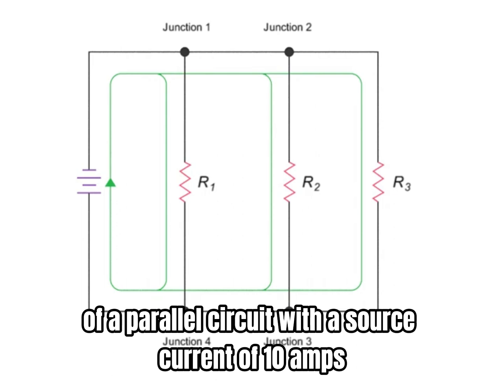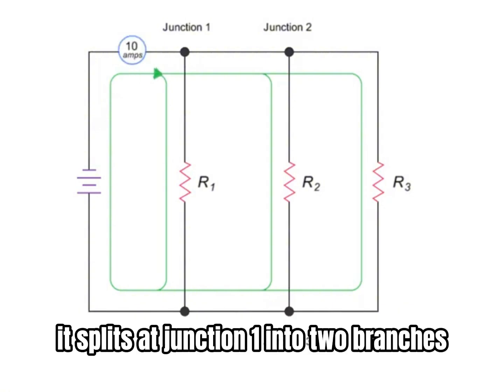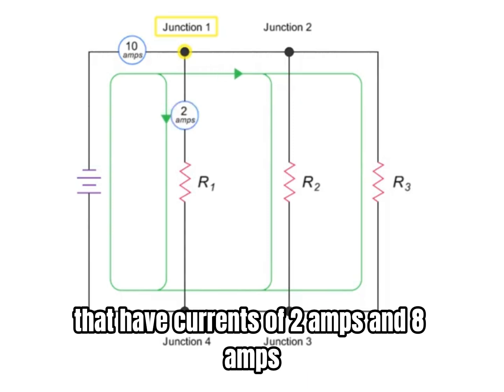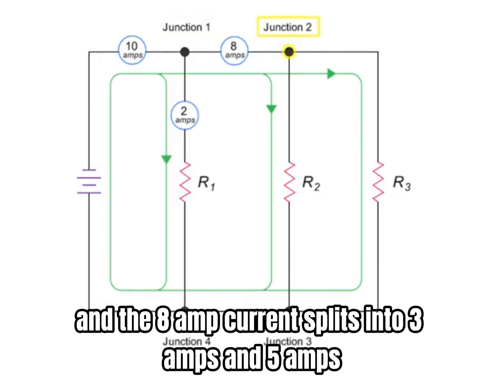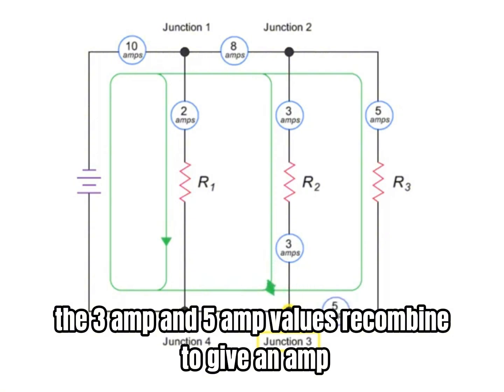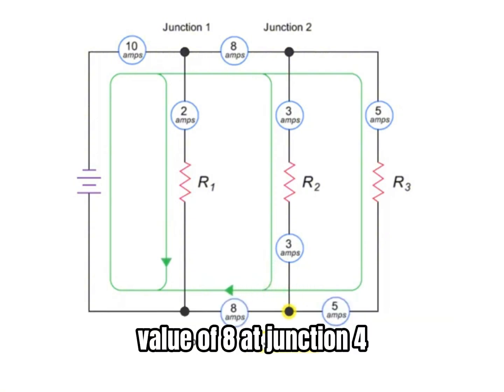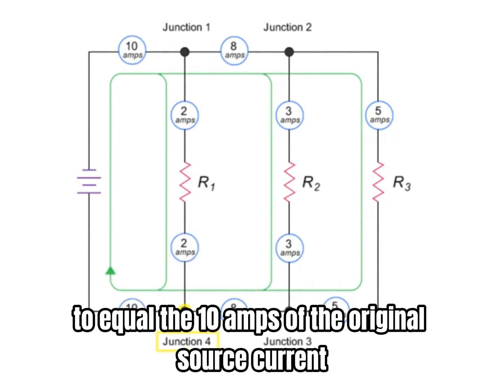current of 10 amps. As the 10 amp current travels away from the source, it splits at junction 1 into two branches that have currents of 2 amps and 8 amps. The circuit branches again at junction 2, and the 8 amp current splits into 3 amps and 5 amps. As the current returns through junction 3, the 3 amp and 5 amp values recombine to give an amp value of 8. At junction 4, the 2 amp and 8 amp currents recombine to equal the 10 amps of the